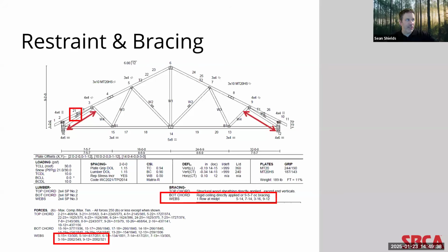So as you can see on this truss design drawing, you have 1 permanent restraint called out at 21, and again, another one at 26, to take care of the midpoint of those 2 web members. And again, you'll see these 2 at the midpoints of these other 2 webs.